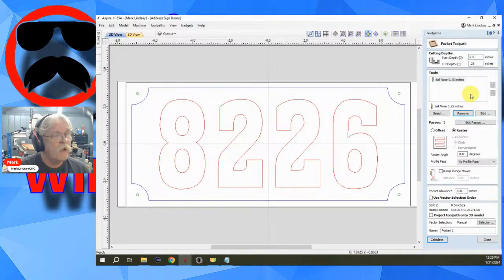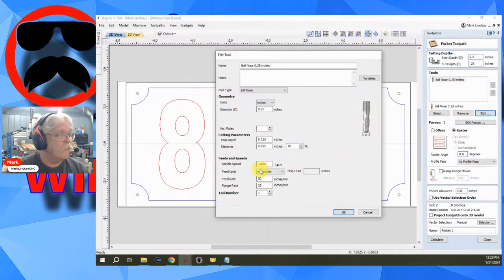All right. Now I've already messed up. Let me go back here to this ball nose bit. I'm going to edit, and I'm going to change my step over to 91%. Right now you're going, what the what?